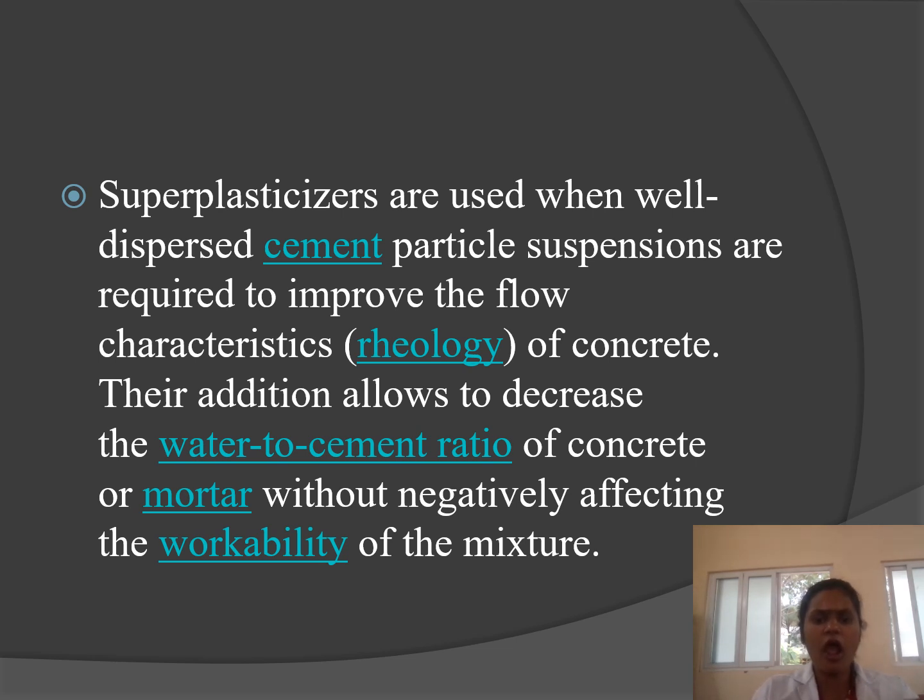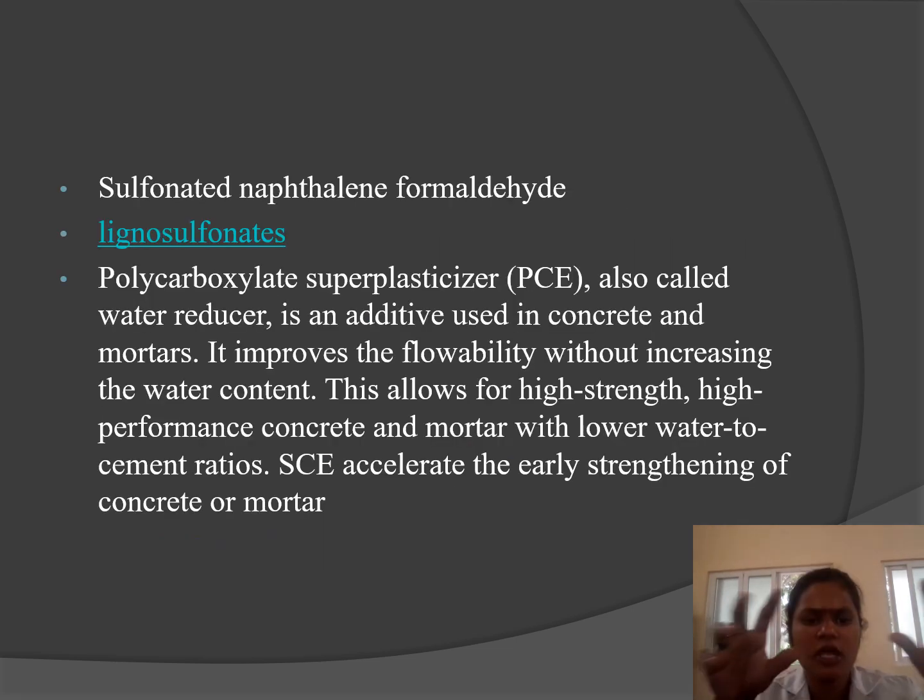The addition allows a decrease in the water cement ratio of concrete or mortar without negatively affecting the workability of the mixture. So next one is sulfonated melamine formaldehyde. Next, lignosulfonates.